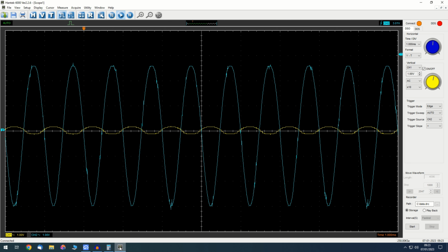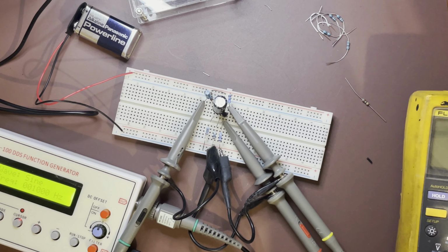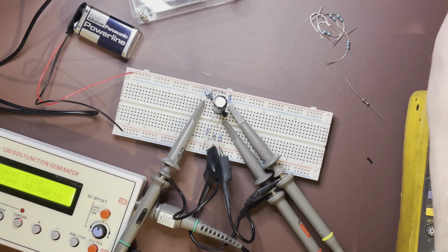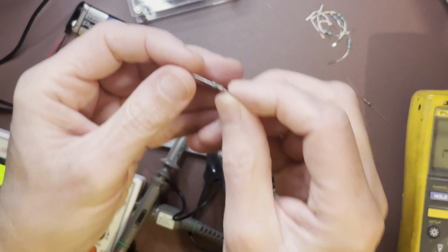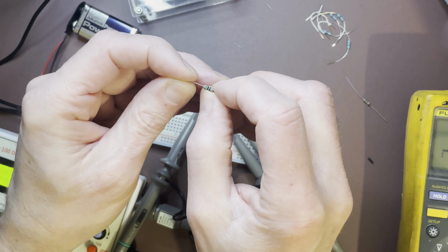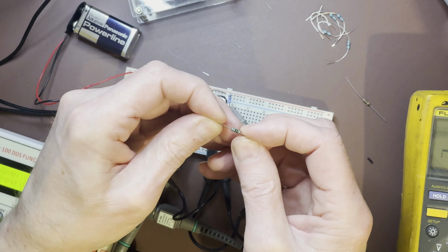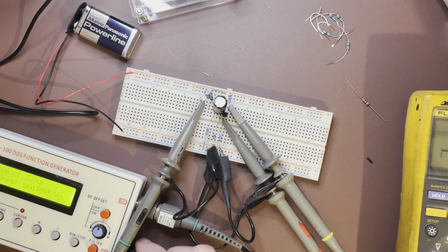It's almost like that 150 ohm resistor wasn't 150 ohms. That's gone way, way higher. No wonder, that wasn't a 150. It's a 750. The first band's purple, not brown. Because of the colouring on it, it's a bit difficult to read. That's why the gain didn't go up as much as I expected.